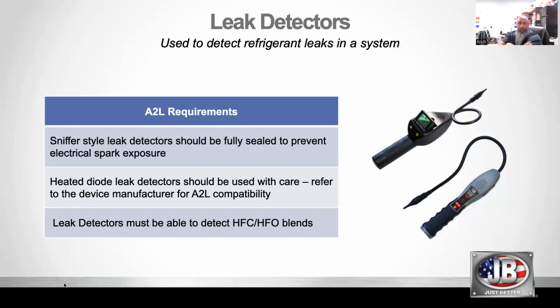And finally, leak detectors. So, most of them are sniffer types out there. The heated diode ones, but a little bit of care because you've got a heated diode, and obviously that's a heat source. But when we look at how much heat is actually required to ignite an A2L, I mean that's not really going to be an issue. But refer to the manufacturer and check that they've certified it for A2L. And obviously they need to be able to detect the HFO blend.